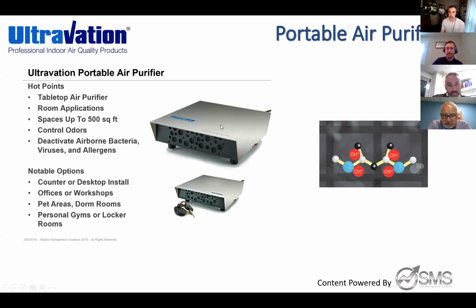There's actually a washable air filter in there, and there's a small UVC lamp. And then you can see there's actually like a grid behind those holes that are drilled in the front of it. That's our carbon bricks that have been treated with titanium dioxide. So this also creates the photocatalytic oxidation. But because those are carbon, it's a zero ozone product. So it's not giving off any ozone.